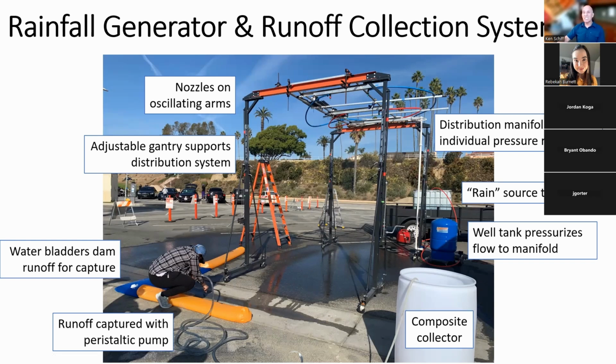But basically, we're not missing any of the runoff. So there's no inference from event mean concentrations or any of those kinds of things. It's the entire storm in a 55-gallon drum. And of course, all the parts are Teflon and those kinds of things, non-contaminating.